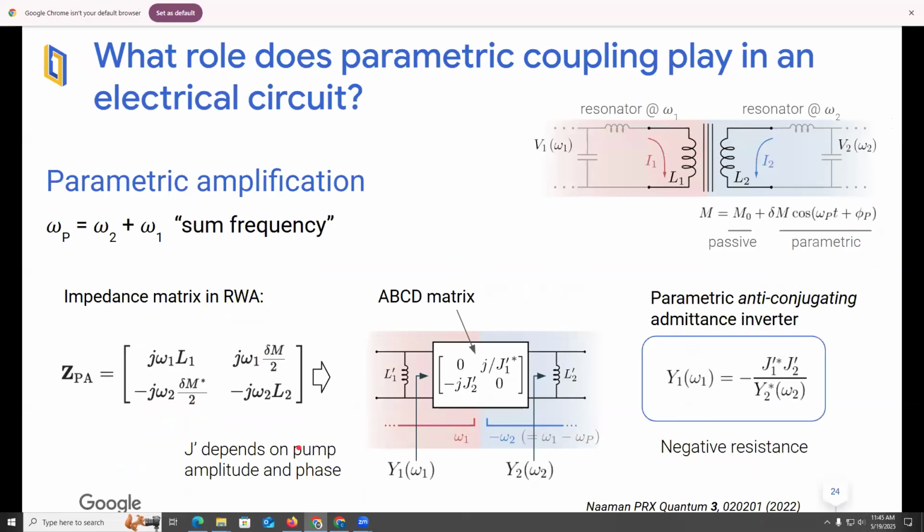So far I've talked about nonlinear simulation with actual device models. And I want to show you in the last few minutes that that is not always necessary, because sometimes we want to model just the microwave circuit, maybe just the small signal limit of these circuits. What we can do in this case is understand parametric interactions as an electrical circuit.